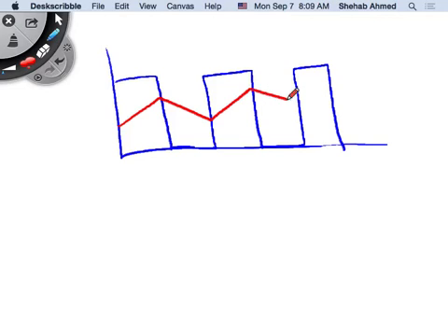This blue waveform has a DC component plus a significant amount of AC components, because of all these transitions. It's like the impulse function, so it has a lot of frequency components. For the square wave, I have the Fourier series sheet, and you can write the components of the square wave from DC all the way to a very large number.